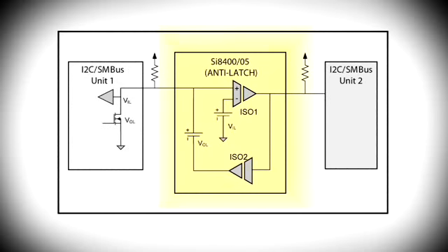The A side output low, VOL, and input low, VIL, levels are designed such that the isolator VOL is greater than the isolator VIL to prevent the latch condition. The reason I chose the A side facing the Si8452 is that the VIL level of the Si8452 is compatible with the special VOL level of the Si8405.